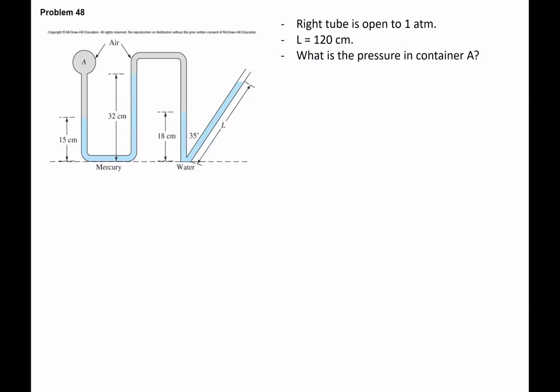Here in this problem, we are after pressure at this tank A, at container A, and the point that this problem is trying to teach is that you can ignore weight of air comparing to weight of mercury and